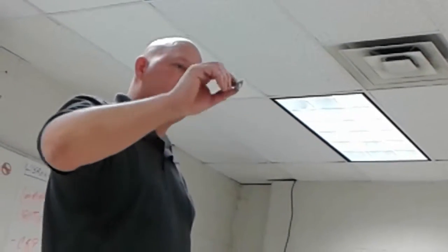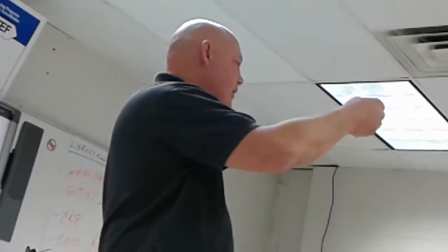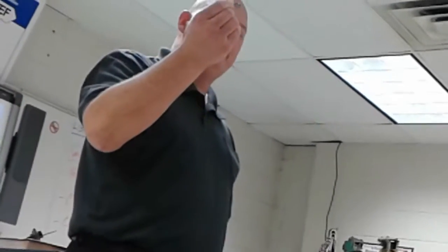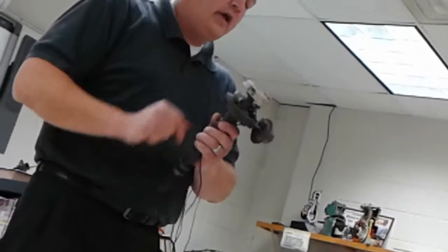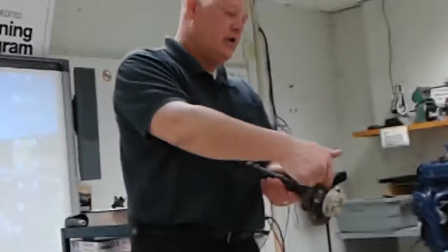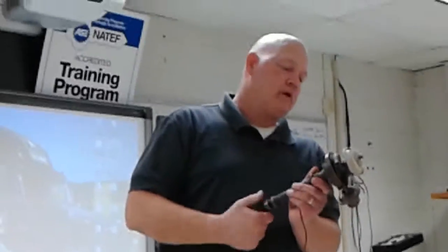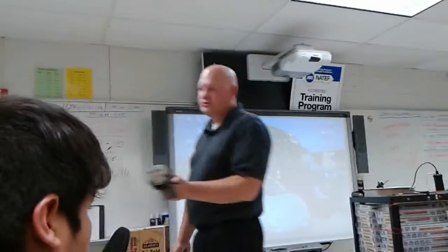You know, we were talking about circuits last week. So, turning on and off. Now we got contact, we have electricity flowing through the primary. When it's open, oh, now this circuit's off, the primary is disabled, the magnetic field collapses, we get the spark. Okay? So I'll let you pass this around, you guys can spin this, and you can see those points right there when you're spinning it, how they open and close, how there's a little bolt-shaped, octagon-shaped thing in the middle of this. When that point comes around, those breaker points pop open, and that's when you get the spark.